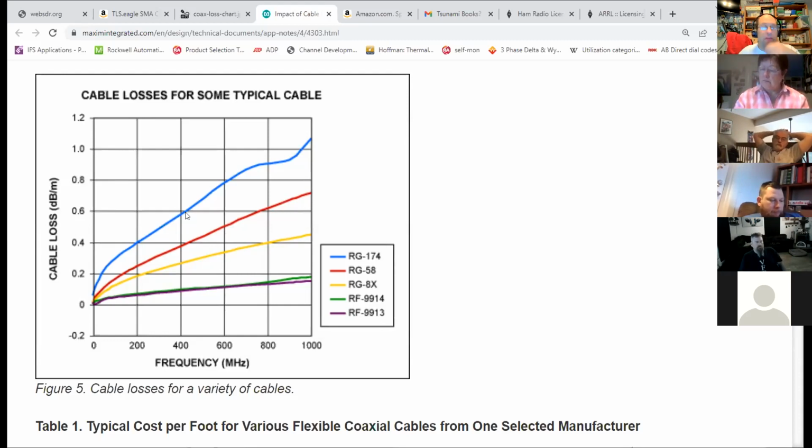Okay, so now that might still be okay. But now let's crank that up to 1,000 watts. If you have 30 decibels of loss, that means your 1,000 watts will produce 1 watt coming out of the other end. Where does the other 999 watts go? It cooks your cable. Your cable's already really tiny, and now it's just turned into a 1,000-watt heater, which will probably destroy the cable. So there's a power handling capacity that's associated with cables as well.